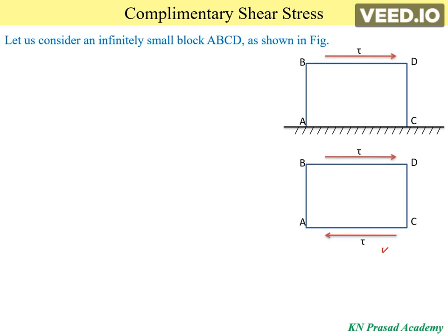Now the question is, is the block in equilibrium condition? Many students will say, yes sir, it is in the equilibrium condition, because we are applying the shear stress tau and a reaction force of equal amount of tau is generated in the opposite direction. So the block is in equilibrium condition. But the answer is no. The block is not in equilibrium condition.